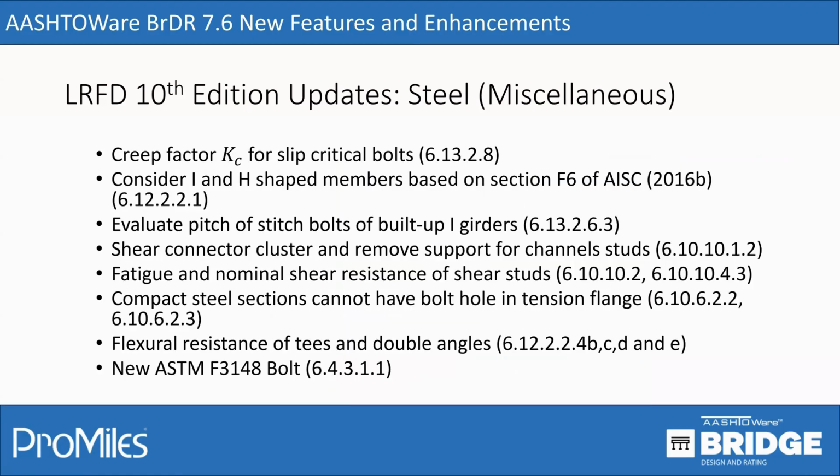Moving on to some miscellaneous updates for steel. There were some updates for considering the creep factor for slip critical bolts. There were also some updates for I and H shape members for considering flexural resistance about the weak axis based on section F6 of the AISC manual.